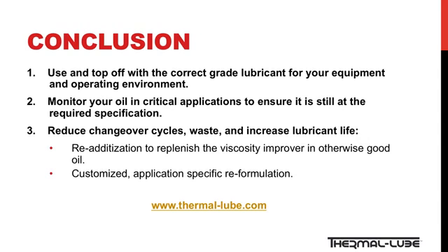Three, if your oil is relatively clean, for example with no soot, Thermalube can provide options for reducing changeover times, disposal, and environmental waste, and increasing lubricant life. Consider readditization to replenish the viscosity improver in otherwise good oil, or a customized application-specific formulation.